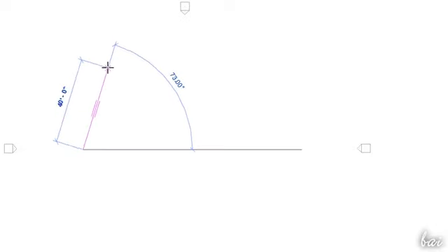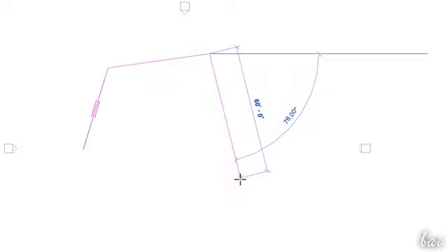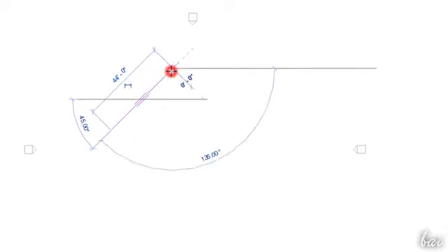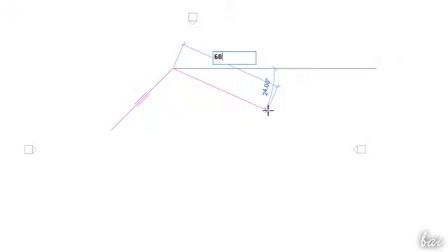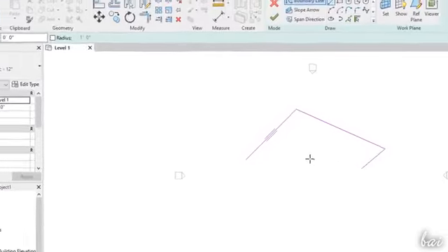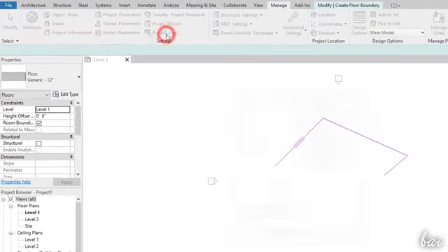Revit has several drawing aids to support your design. Measurements are provided on sides, radius, and also angles with respect to the horizontal direction. You can also type from your keyboard to insert precise values on the current drawing step. If the units used are wrong, you can define these by going to Manage and then to Project Units.